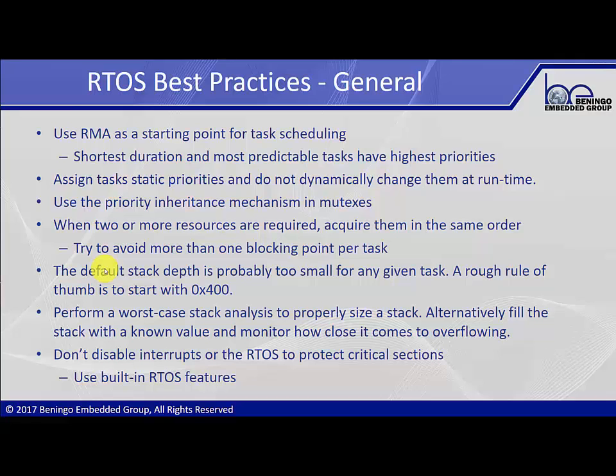A lot of real-time operating systems will have a default stack depth that is usually too small for any given task. A rough rule of thumb is to start with hex 400 for the size of it, but you really got to look at your task and see what you're doing. If I'm blinking an LED, 256 bytes of stack space is just going to be way too much. But if I'm running a USB stack, starting with just a kilobyte isn't going to make any sense. I probably want to start with 2 kilobytes worth of stack space. So, start out with a best guess from experience, but follow it up by performing that worst-case stack analysis under load to actually see what's being used in the system.